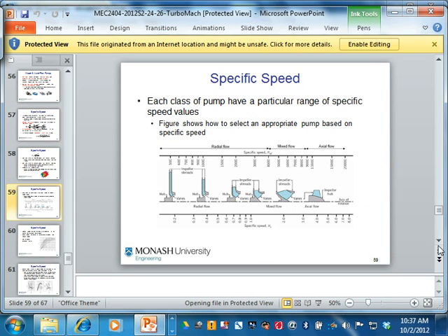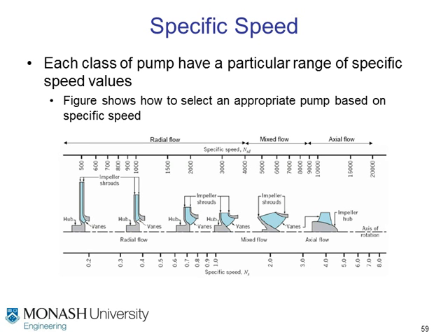All right. So the graph here looks like this. Okay. So for high specific speed, high flow rate, there. This is your specific speed here at the bottom. After you put in the numbers for omega, Q, and the head, all right, you can calculate the specific speed. So for a particular application, you calculate the specific speed, then you find it.